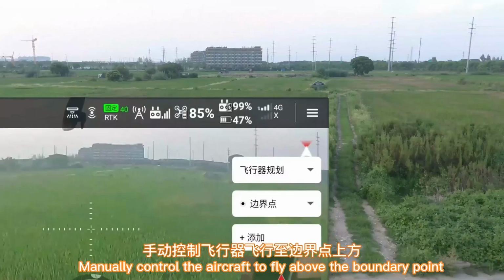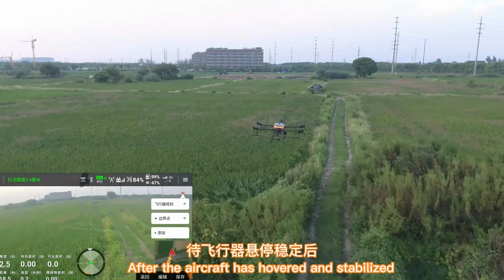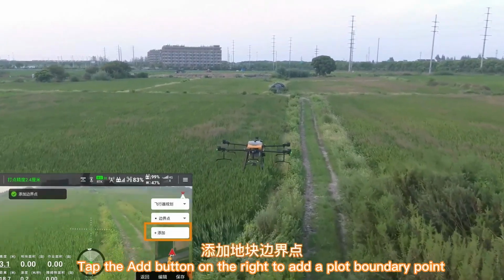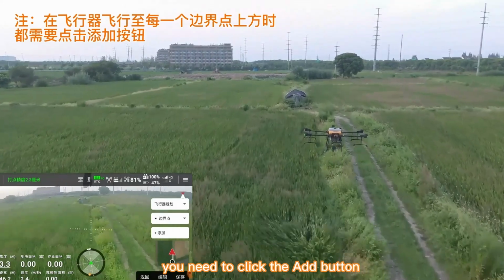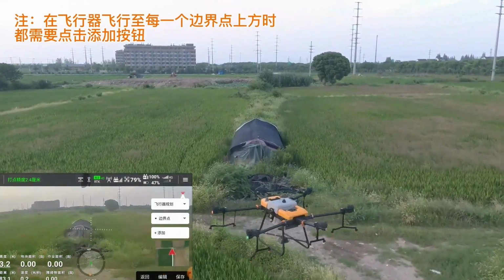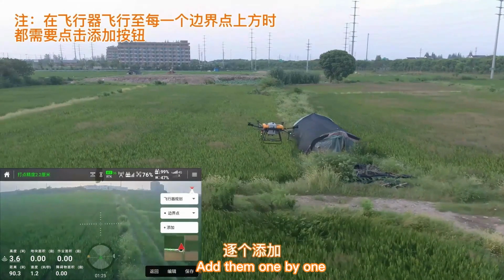Manually control the aircraft to fly above the boundary point. After the aircraft has hovered and stabilized, tap the Add button on the right to add a plot boundary point. Note when the aircraft is flying above each boundary point, you need to click the Add button. Add the boundary points in the working area in order, one by one.